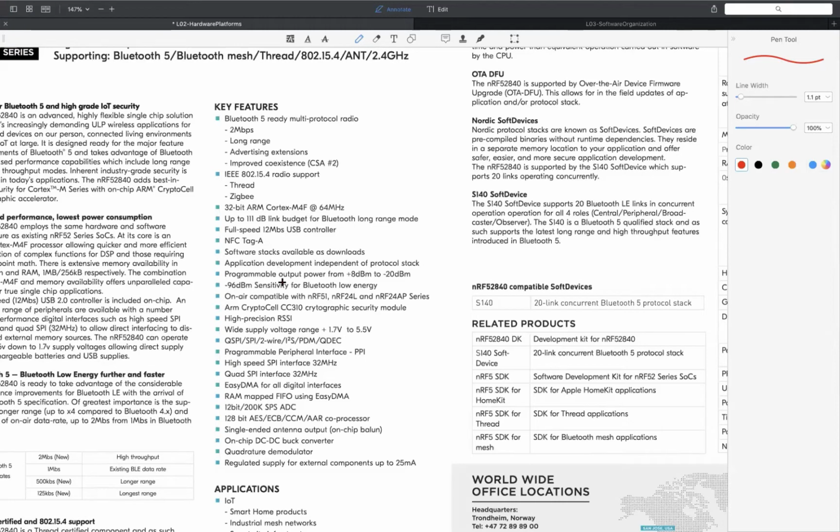Let's see what else. You see a whole bunch of other details. For the radio, it also tells you very high accuracy of the receive energy. RSSI is receive signal strength indicator. What do you think we can use this for, RSSI? Why is it important to measure? Positioning, maybe? Yeah, positioning. And more broadly as an RF sensor.